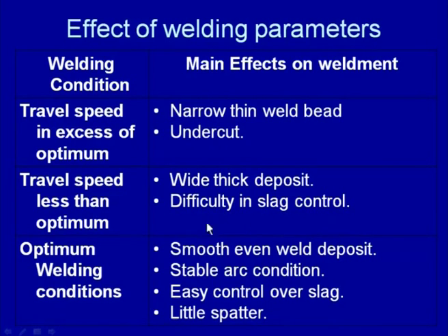So, when we select the optimum welding current, optimum arc voltage and optimum welding speed, this in turn results in the desired amount of heat being supplied to the base metal for proper penetration, melting and the development of a smooth weld bead geometry.